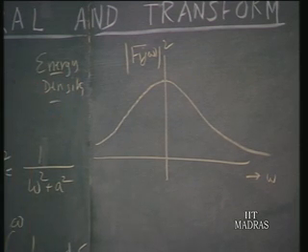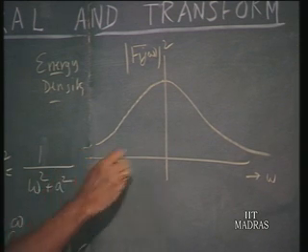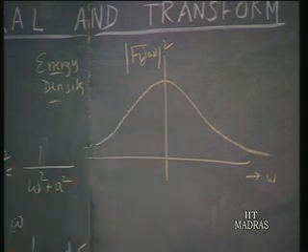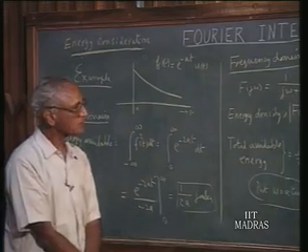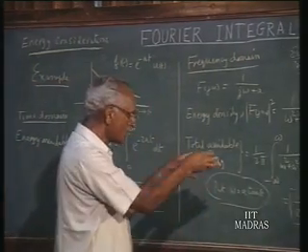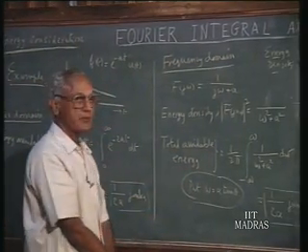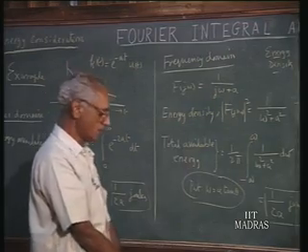So this gives us an idea of where the energy is concentrated, at what frequency bands there is more energy. Now as you can see, there is a lot of energy in the low frequency band centered around the DC. At higher frequencies the energy is somewhat less. This additional information is obtained through the Fourier transform analysis as compared with the time domain analysis. Let us see how such a concept can be made use of in practice.